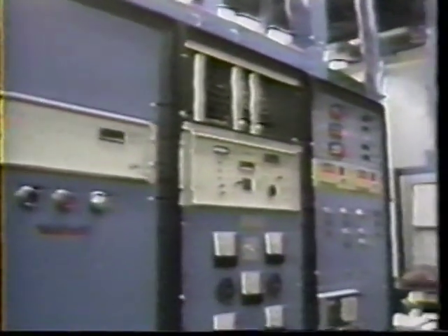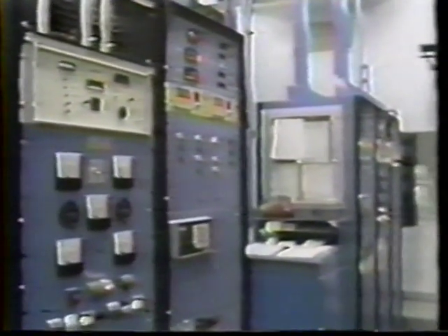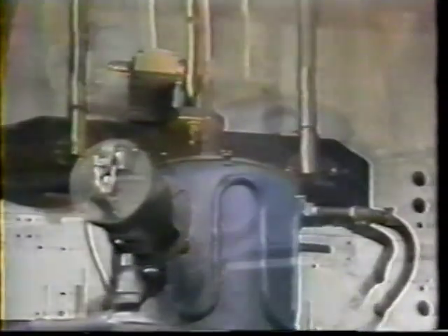The strength of a newly drawn fiber, its dimensional accuracy, and its surface condition all depend upon the drawing process. AT&T Network Systems draws light guide fiber using computer-controlled drawing towers. First, a solid preform, which has already been quality inspected, is vertically mounted to a motor-driven feed mechanism. This preform is then slowly lowered into an induction furnace whose temperature is closely monitored by a computer.